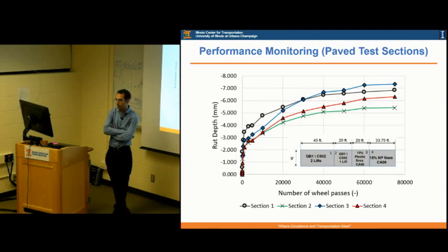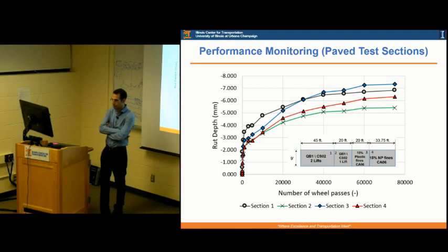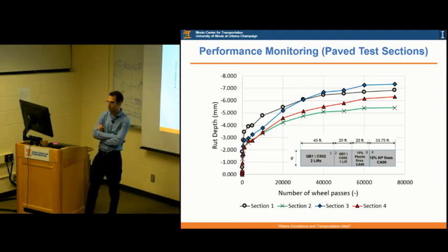In what sense? That QB is, for example, dolomite, not limestone? Oh, dolomite and limestone, they're basically the same. They're all carbonatic rocks that we have in Illinois, sedimentary carbonatic rocks. So I don't think there's going to be much difference. We actually tested four different quarry sites in the previous project, and found little differences overall from primary, secondary, tertiary crusher.